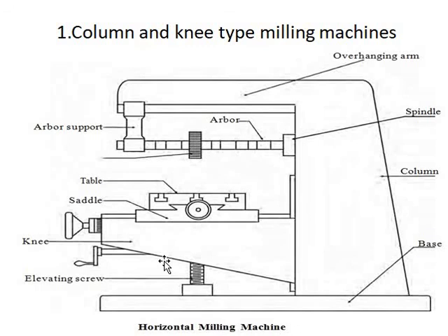Next comes the very important thing, that is the spindle. It is a large shaft located at the top of the column, having a tapered hole in front of it. The tapered hole is used for holding arbors and cutting tools. Next comes the overarm. What is overarm? The portion at the top of the column above the spindle is called the overarm. Overarm is used for supporting arbors and can be moved forward and backward.